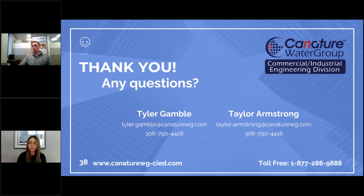Okay, so Ken just wrote back, aragonite is the result of altering the structure of calcium carbonate. So kind of what I had mentioned, there are technologies out there that are not water softeners, they're water conditioners is the best term for them. What they're doing is altering the structure of the hardness, so that way it doesn't do any scale forming. Once again, there's emerging research coming out on them as to their efficacy. I have heard of some people using them with RO systems and having good results, but I've also heard about those kinds of systems being completely ripped out because they didn't work at all. So it's kind of a toss up.